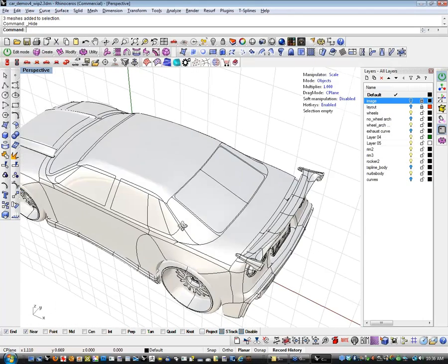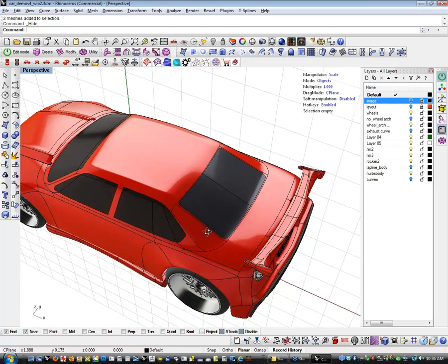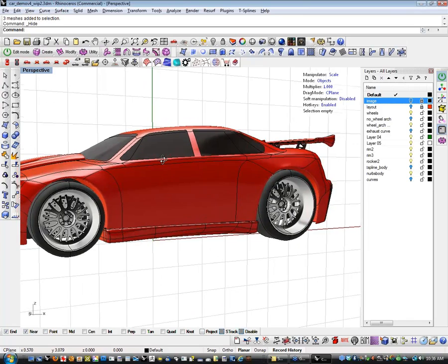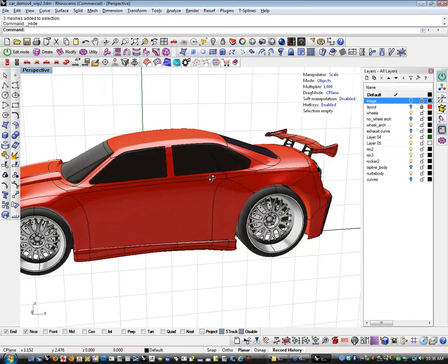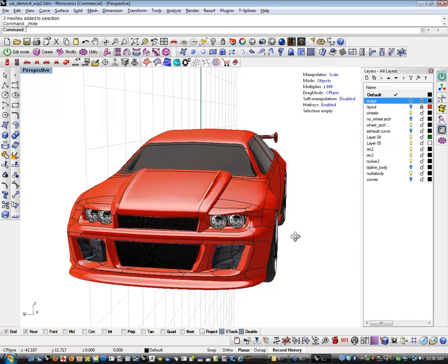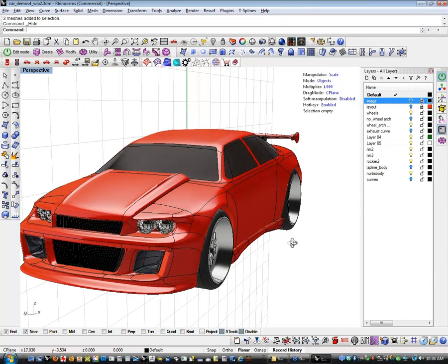And then to finish it off, basically, to make the window glass and stuff after I converted to NURBS, I just went ahead and did some trimming curves in here. And you can continue to detail the model from here. The upside is, before I did this, I made sure and saved the T-Splines parts on a different layer.